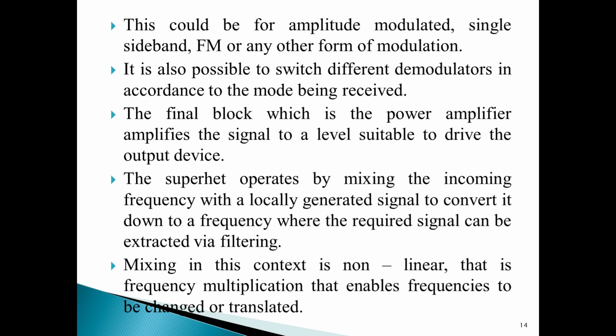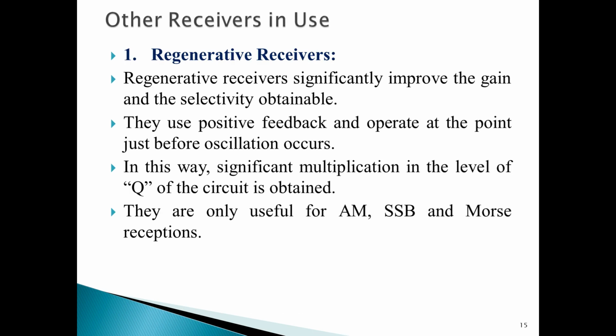The Superhet operates by mixing the incoming frequency with a locally generated signal to convert it down to a frequency where the required signal can be extracted via filtering. Mixing in this context is nonlinear, that is, frequency multiplication that enables frequencies to be changed or translated.